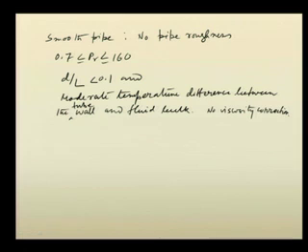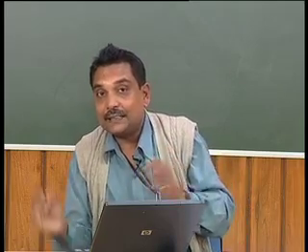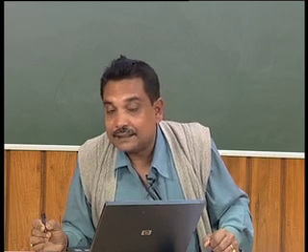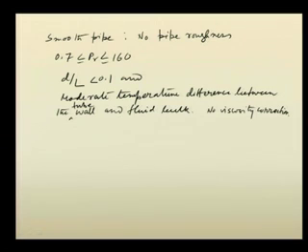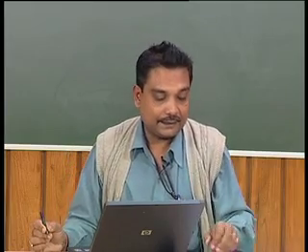Then the Prandtl number has to be within a certain range, 0.7 less than or equal to Prandtl less than or equal to 160, and D by L should be relatively low, that means the length should be sufficiently long, so D by L is less than 0.1, and a moderate temperature difference between tube wall and fluid bulk, that means not much viscosity correction is involved.